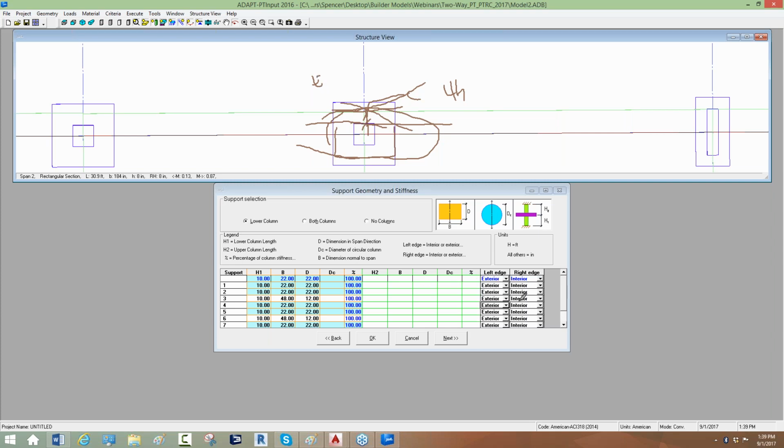If you use interior condition, and this is a similar condition, you have the same exact condition here and over here, but I have different tags, exterior and interior. In this case, this program says this is an interior condition, use a 4-sided critical section for this. So you would get actually a different result between these two columns by having these two marked differently on each of the columns. So you have to be careful with this.